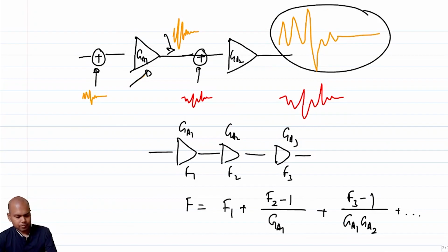if we have a cascaded system, the input referred IIP3 is going to decrease if we have gain in the subsequent stages further down the signal chain, and your noise figure will not get affected much, because the noise figure is going to be determined by the noise figure or the noise factor of the first stage, right? So these are the two important things that you need to keep in mind when you evaluate a block,